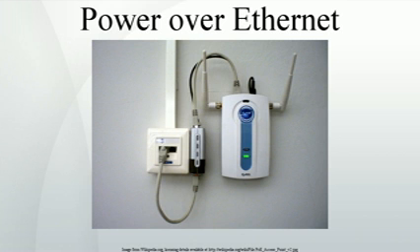The PD has then to provide Ethernet link within 5 seconds to the auto-negotiation mode switch port. A later CDP message with a type length value tells the PSE its final power requirement. A discontinued link pulse shuts down power.